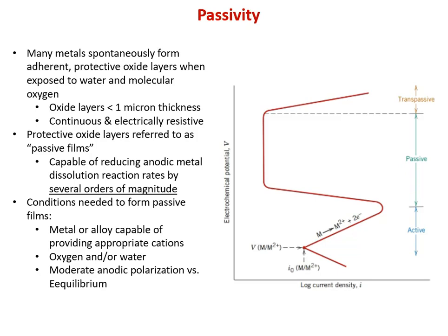So they stop both physical migration of atoms into solution as ions, and they also stop that charge transfer at the interface, therefore basically effectively making your activation polarization infinite or very, very high. So if we were to look at how that would look on a current potential relationship diagram, you'd get something like what we see here over on the right.